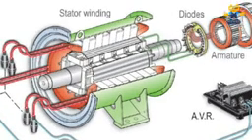In this way our main rotor gets excited, and our main rotor has 4 poles: 2 north poles and 2 south poles, and these positive and negative will excite it and make it an electromagnet. Once this electromagnet rotor revolves inside the stator winding, it will again produce the electrical power, the voltage.